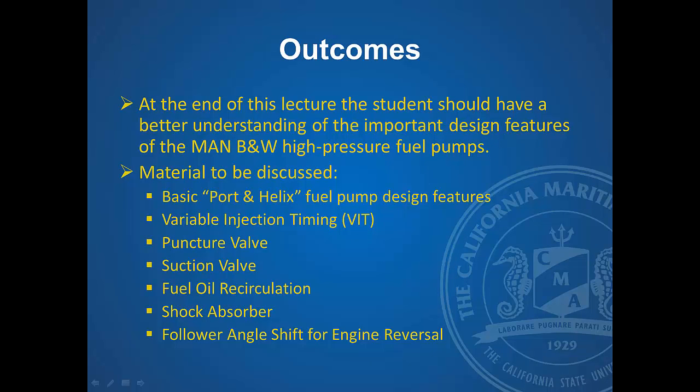At the end of this lecture, the student should have a better understanding of the important design features of the Burmeister-Wain high-pressure fuel pumps. We will discuss basic port and helix fuel pump design features, variable injection timing, the puncture valve, suction valve, fuel oil recirculation, the shock absorber, and for engine reversal, how it shifts the follower angle.